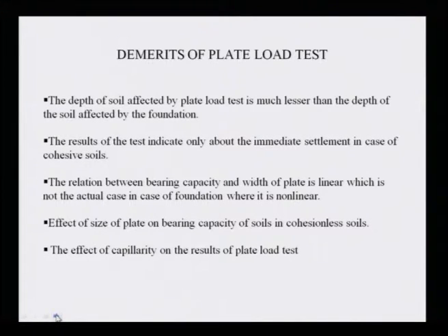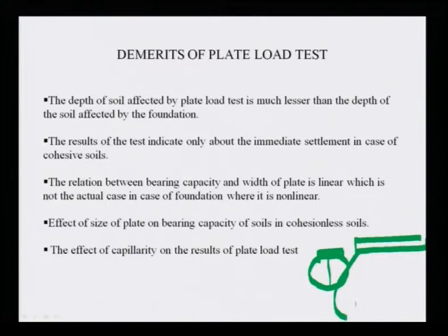What are the limitations? This part I have not discussed. In the plate load test, the limitation is that the depth of soil affected by the plate load is much lesser than the depth of soil affected by the foundation. If I say this is my plate, the depth is affected only over a very small area, and this is my footing, that means it is affected over a much larger area.